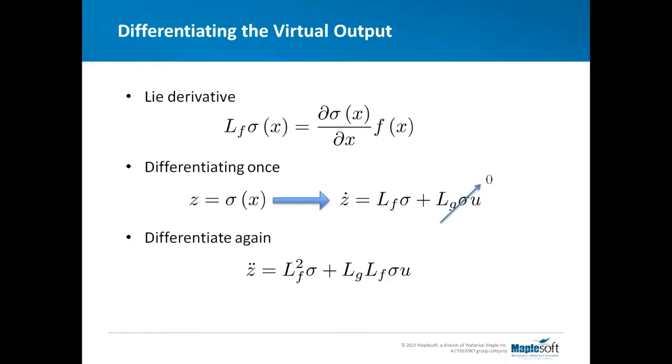Because it's a mechanical system that has a certain form, and it's a second order system, the first term here goes to 0. And that's a result from the literature, and I've got a link to the paper on the next slide. But if you're not familiar with control design, don't worry about it. For those of you that do know about it, it says that the relative degree of this system is not 1, it's higher than 1, which makes sense because mechanical systems are second order systems.